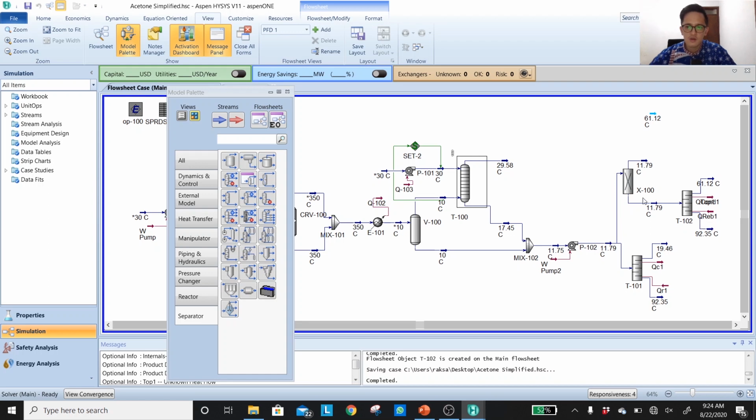In practice, we don't really have this column in the plant, but the process itself can be done in several locations. For example, when we have a distillation column, usually we will have an overhead condenser before it's sent to the reflux drum. And the hydrogen, if we maintain the temperature at about 61 degrees C at 1.2 bar, will not be condensed.